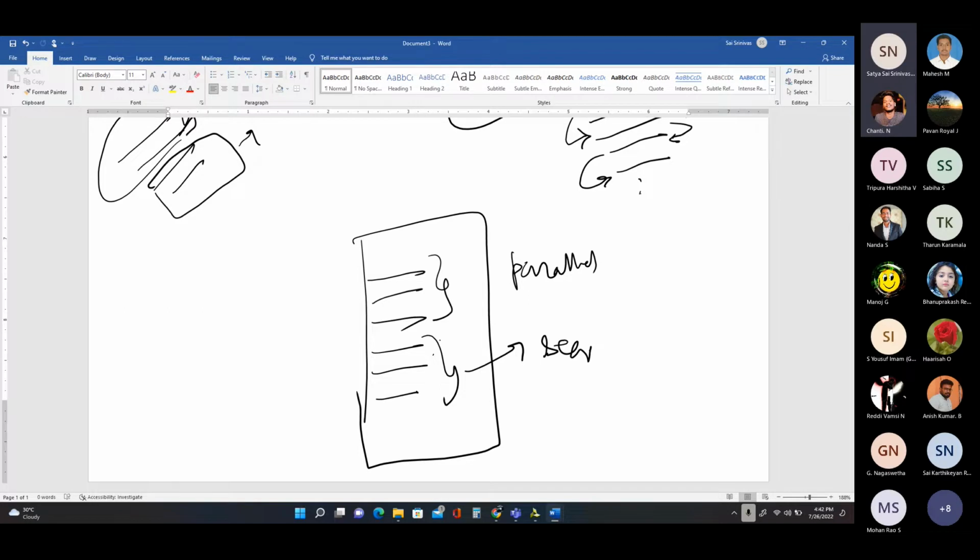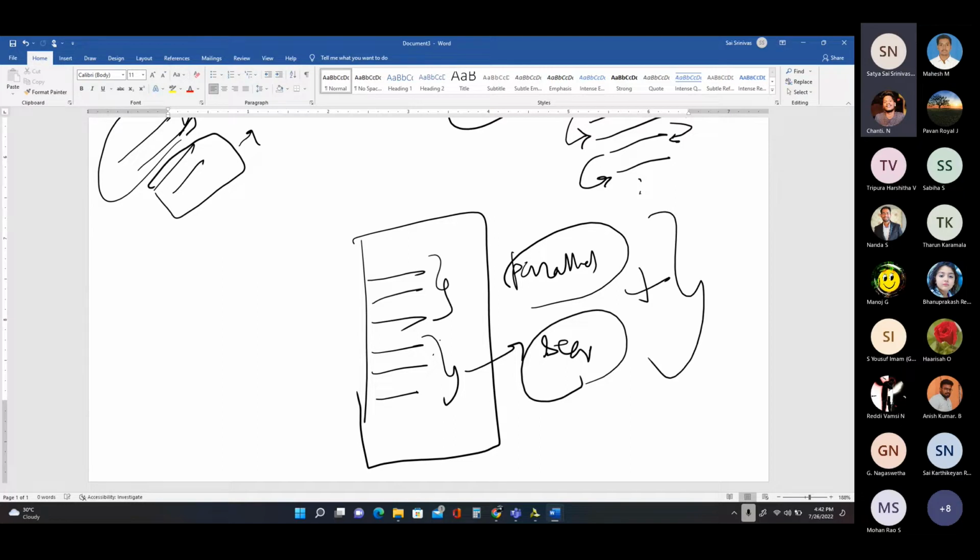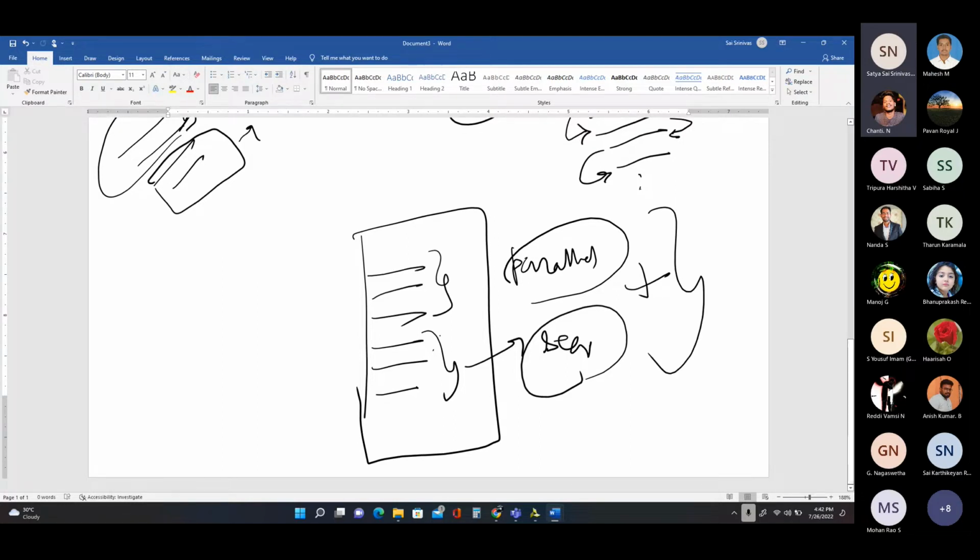It doesn't mean everything will run in parallel. Some part of the functionality also runs sequentially. In C, it is completely sequential, but Verilog is sequential with parallel. So, in order to avoid this confusion, Verilog language uses the concept of procedural and non-procedural statements.